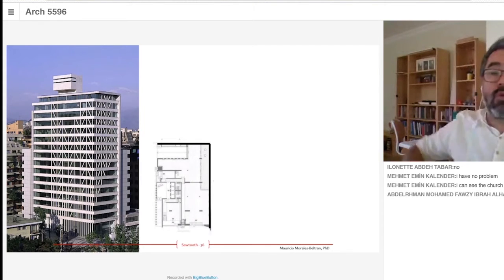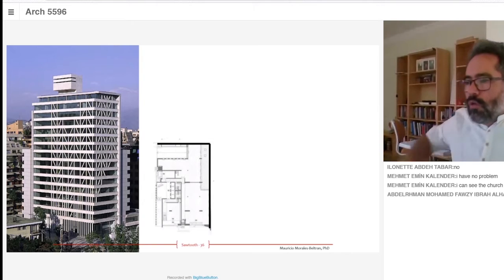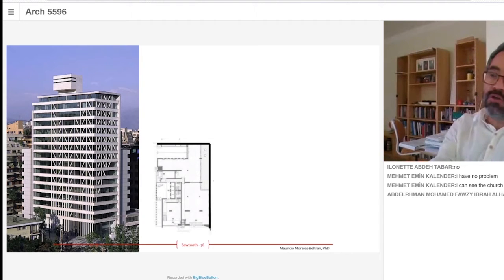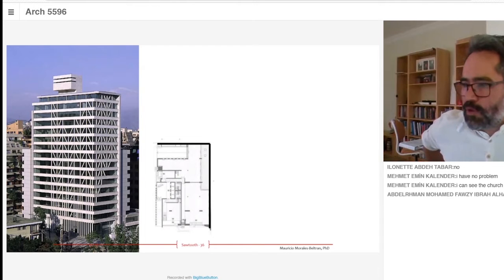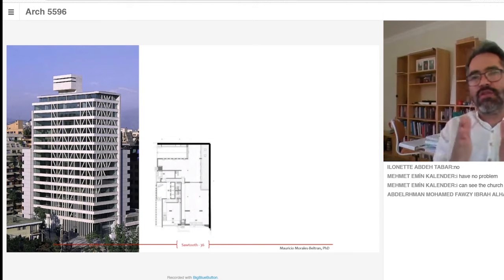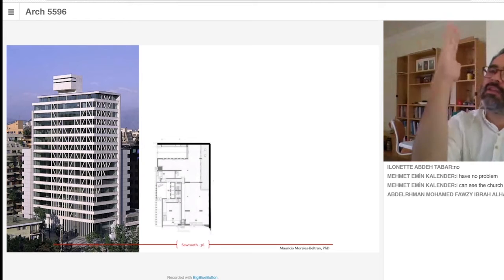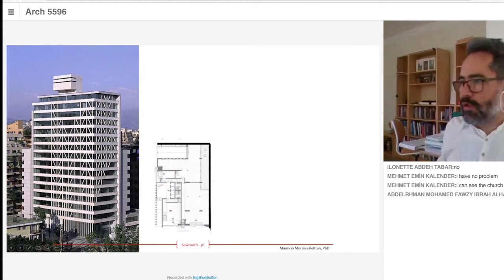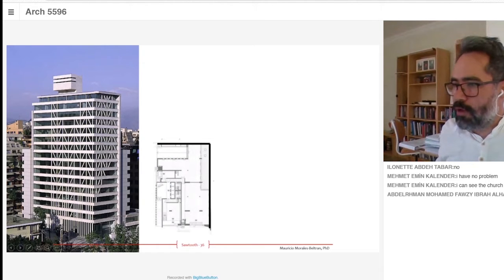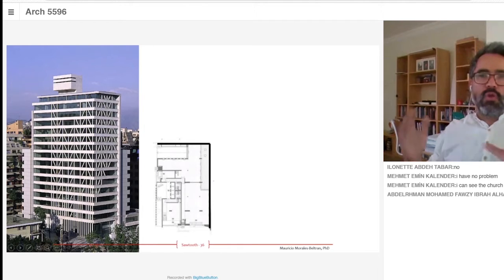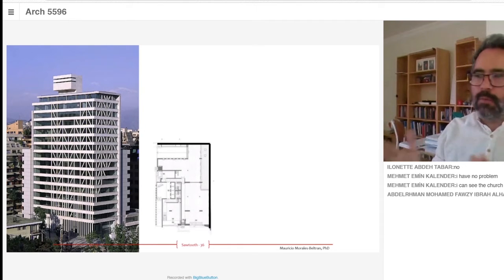The logical solution from the seismic design perspective is to balance this distribution: take this thick line that is on one side and put it on the other side. So if this is one thick line, we should maybe take half and put it here on the other side, and then half of this one and put it here. In that way, you will have equal stiffness, but now distributed around the perimeter of the building.